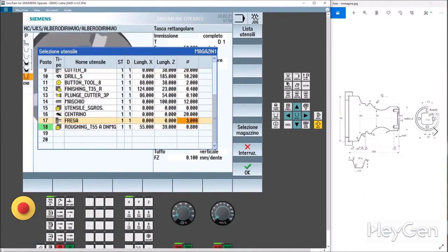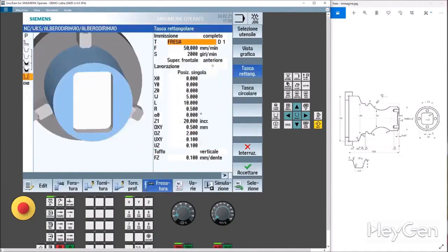So we need to do, however, radius 4, so diameter 8. Let's take an 8 cutter. That's perfect because this is a diameter. So, okay. We'll work at 2000 RPM, 50 millimeter per minute.